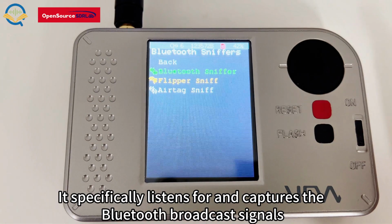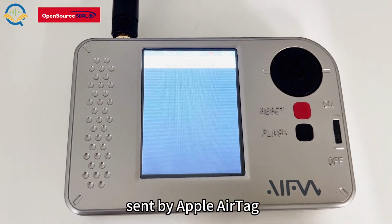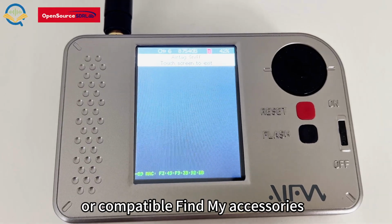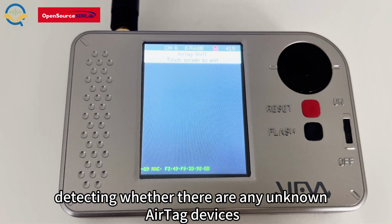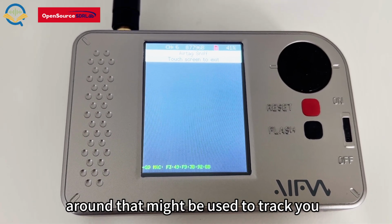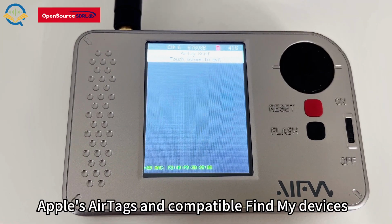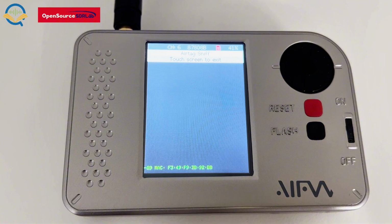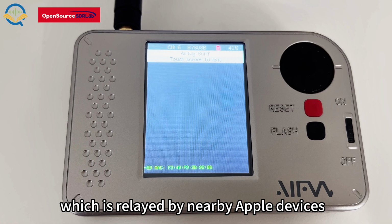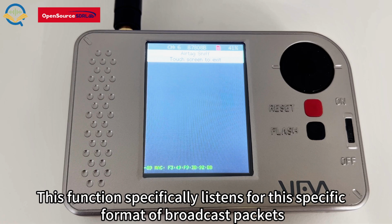AirTag sniff specifically listens for and captures the Bluetooth broadcast signals sent by Apple AirTags or compatible Find My accessories, detecting whether there are any unknown AirTag devices around that might be used to track you. Apple's AirTags and compatible Find My devices regularly broadcast an encrypted data packet via Bluetooth, which is relayed by nearby Apple devices and reported to iCloud. This function specifically listens for this specific format of broadcast packets.